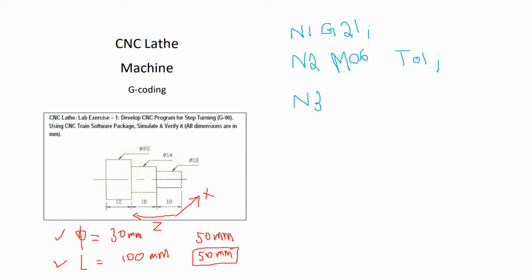Okay, G00. This is specifying the origin. Like I told you, G00 is rapid positioning. Typically G01 and G00 are the same, but G00, like the word says, is rapid, it's quick, so it will bring the tool quickly to that position. So if your tool is very far away from the workpiece and you want to bring it to the position quickly, always specifying the origin with G00 is better. This is what I have understood from many examples and operations as well.